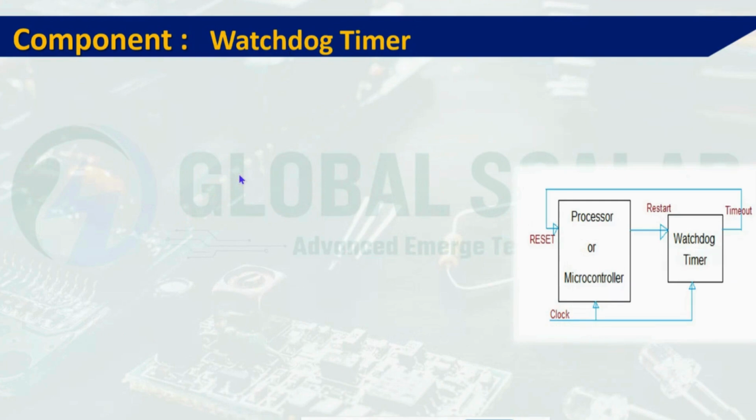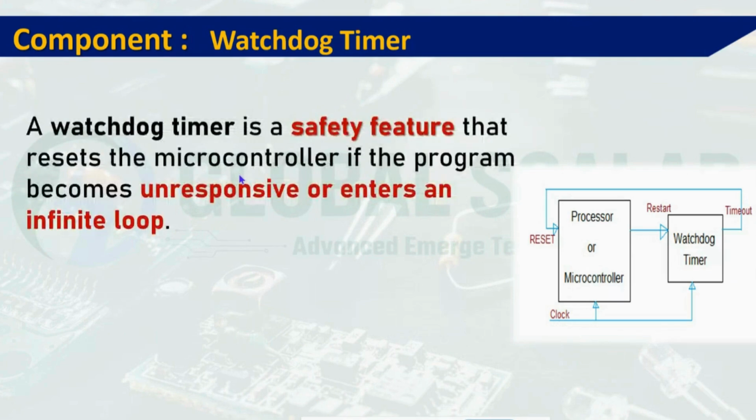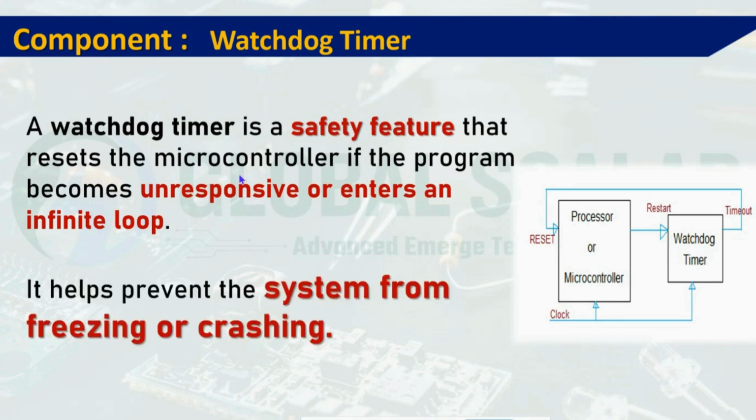So we have a watchdog timer. The watchdog timer is specifically a safety feature. It will reset the microcontroller if the program is running infinitely, or it got hung, or it is not responding properly on time. So the watchdog timer is one pin. When we enable it, this will reset the complete microcontroller.